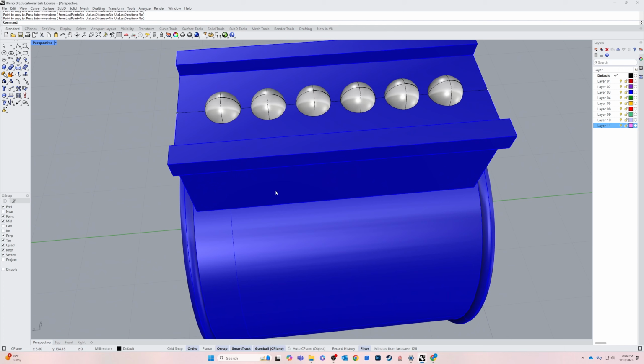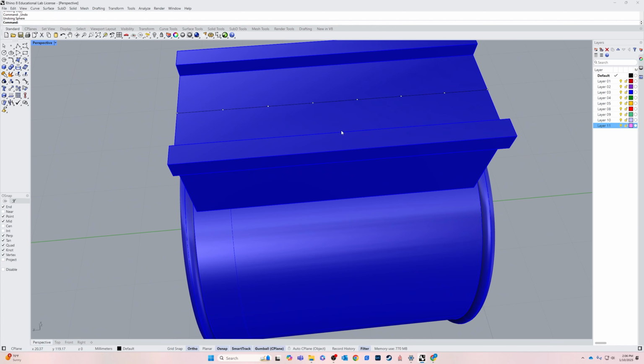Okay. So you want me to do that again? Let's do it again just because it's a little confusing. So we have our line, curve, divide. It's the command. Enter. Now reverse that segment. 7. Enter. Okay. Out of the command, you can see by the fact it says command here. Make sure your point snap is turned on.